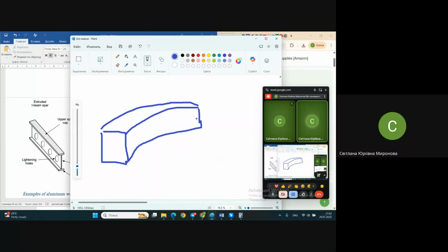Here is a rectangular beam, and as I already told you, this is what bending moment looks like. Look at this: a couple of forces. Here it's extension, here it's compression. And quite clear in cross section, those forces are plus and minus: tension, compression.